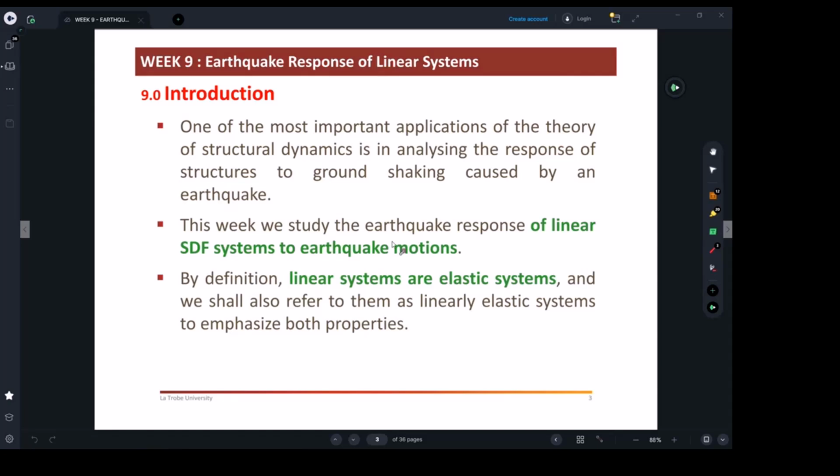This week, we're going to consider that all the vibrations are linear, and that's how we're going to generate the spectral curves. We don't assume that there is non-linearity in the building's behavior, which would only be considered if the building got to collapse, but we don't want to get the buildings to the collapse stage. Whenever we design a building, we always aim for the building to move under the elastic, linear phase. We don't want to get it to failure and then start looking at what's going to happen to it. That's not what we're trying to do.